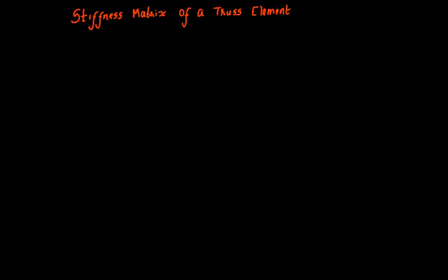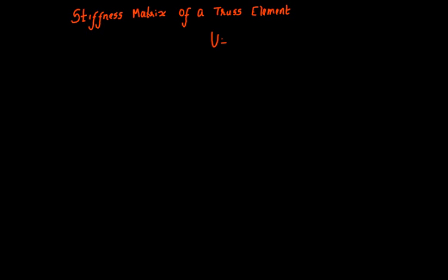And also there is one more video on how you get the formula for strain energy U. The formula for strain energy is U equals half into K into X squared. So the question here is how do you get this formula, because this formula is going to be the prerequisite in order to determine the stiffness matrix for a truss element. We are going to predominantly use this formula, so you have to become familiar with how you actually use this. How is it that you are actually getting this formula?